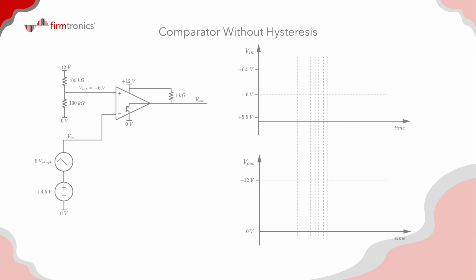The noise can create problems due to the jagged peaks and troughs that occur as the signal is transitioning through the reference level. The noise can also cause erratic transitions on the output, which can create issues for systems where the output is connected directly to a relay or a microcontroller. Relays will chatter, which can shorten their lifespan, and microcontrollers can jump in and out of interrupt routines hundreds of times, which steals valuable processing time from the processor.